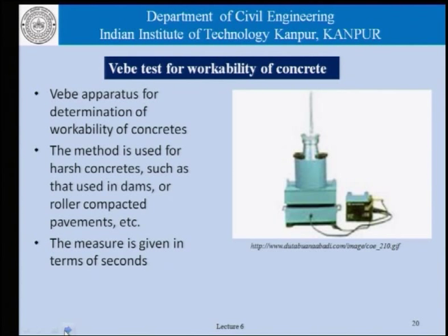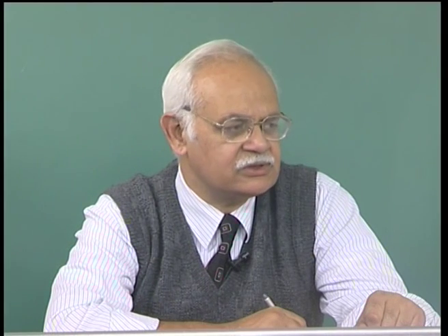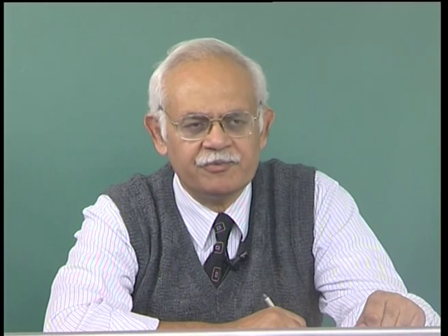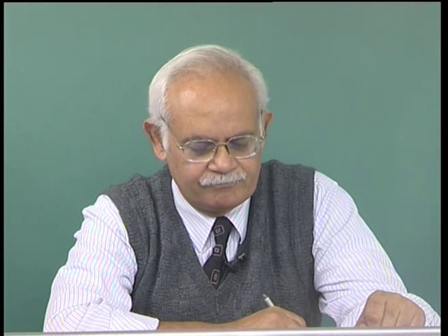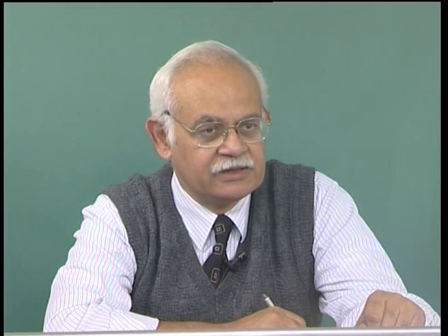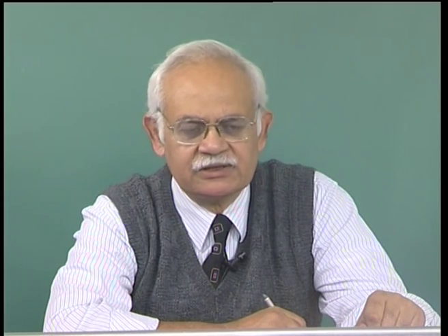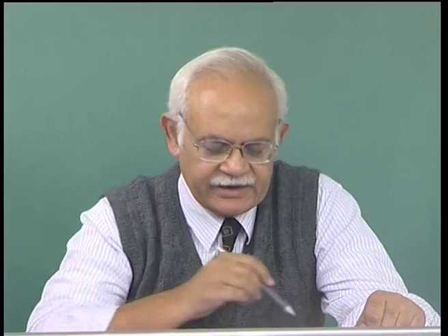For the sake of completeness, this picture here shows the VB apparatus for determination of workability of concretes which are stiff. These concretes are used in applications such as dams, roller compacted concrete pavements, and so on. And the VB test gives us a response in terms of seconds.